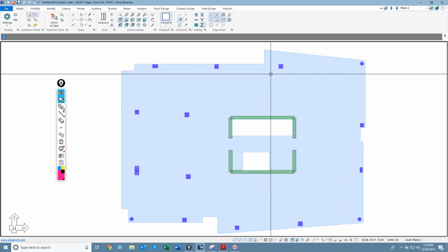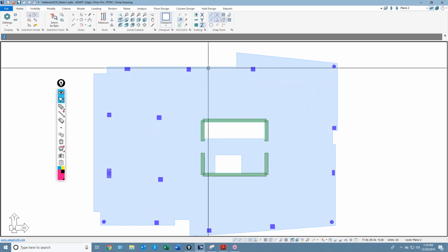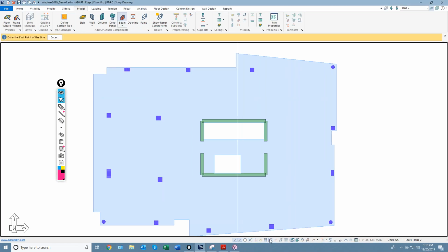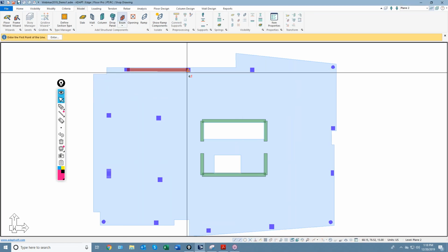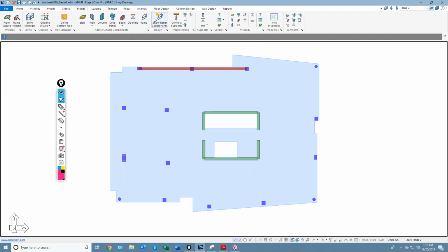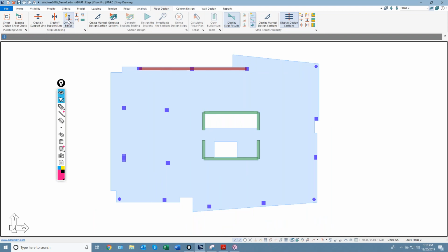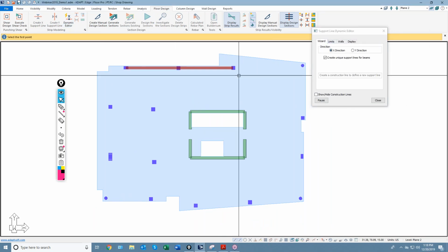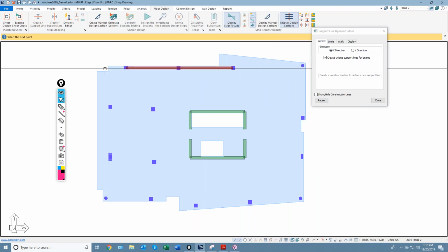If I have a beam along a couple of these frame lines, let's go ahead and model 2 beams here. So I'll go from here over to there and something like this. And going back to the dynamic editor, at beams, if we use the construction line and we snap near the endpoints of the beams.